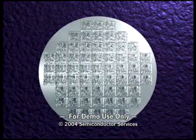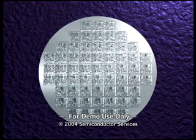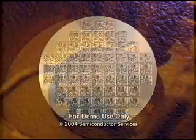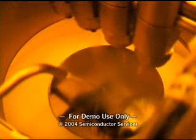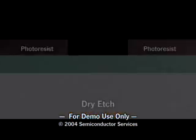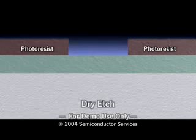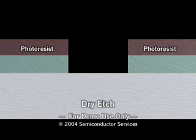After alignment and exposure, the photoresist layer has regions of exposed and unexposed resist. Bringing out the pattern in the resist layer occurs during the development process. Dry etch takes place in plasma etch systems, where the patterned photoresist acts as an etch stencil.